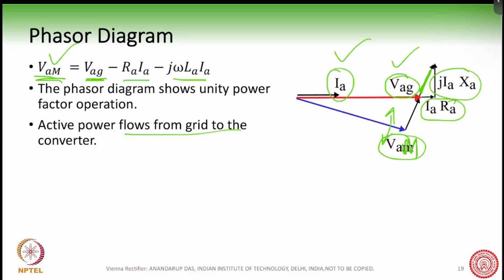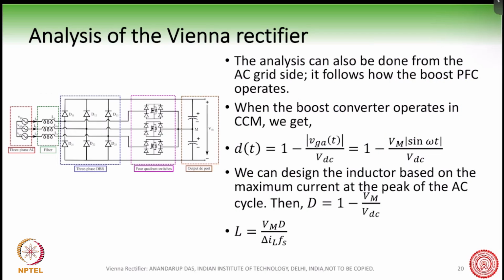Okay, so this is the analysis when we look at it from the AC point of view. Now you can also do the same analysis and you will come to the same conclusion if you do the analysis thinking of it as a boost PFC. So the analysis can also be done from the AC grid side, and it follows exactly how a boost PFC operates.